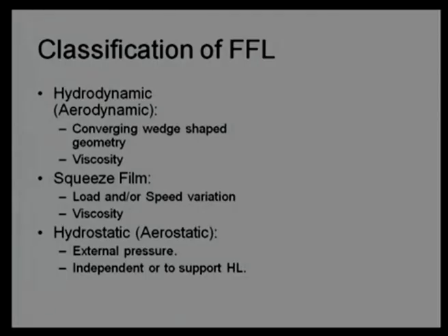As external pressure is supplied or applied, this will be a costly mechanism compared to squeeze film action, compared to the hydrodynamic mechanism. So, often we avoid hydrostatic or we provide only partial hydrostatic mechanism, unless no possibility of developing hydrodynamic action, no possibility of developing squeeze film action.